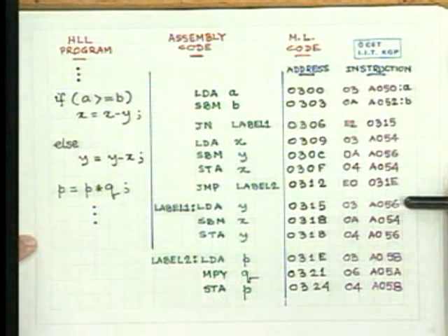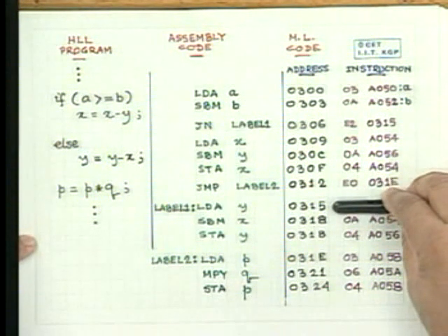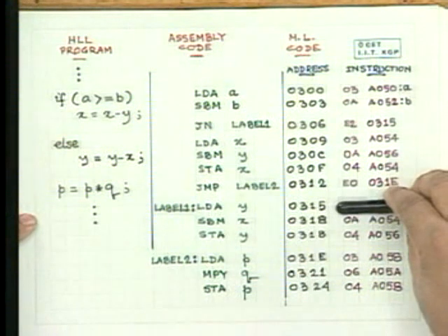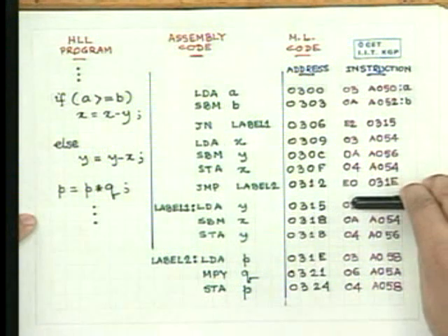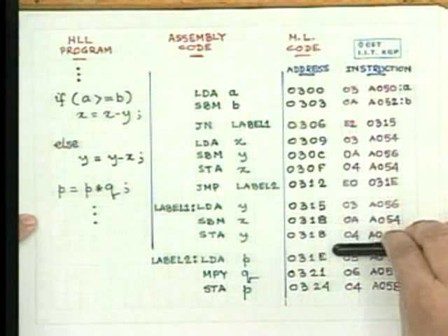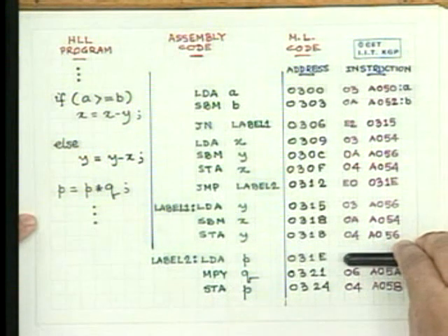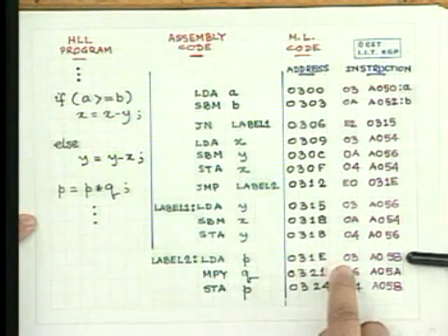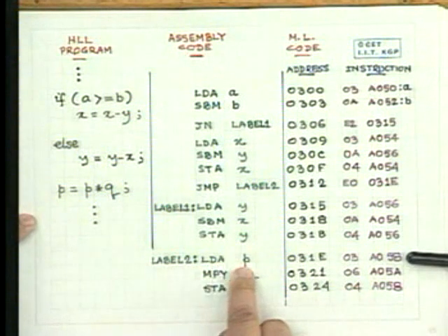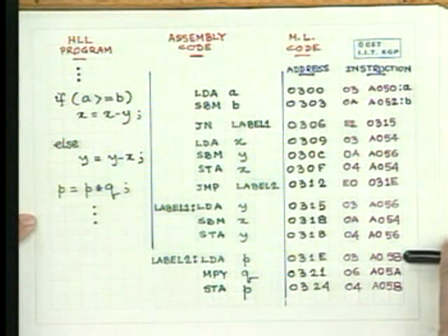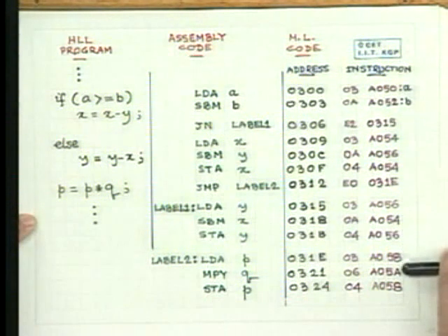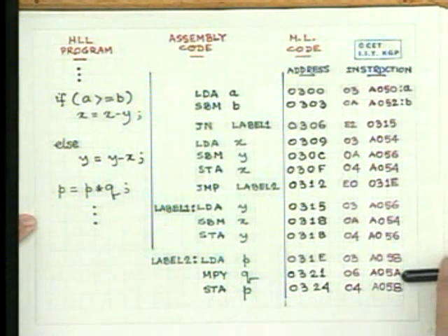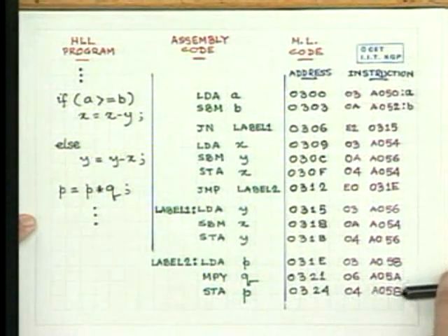As I say, at the beginning of any instruction cycle, the program counter's content gives the address of the next instruction that is executed. Since the program counter will now be pointing to 031E, the instruction execution will start from this location, that is, from the instruction load accumulator. Once it has taken a jump, the program counter will automatically get incremented as every instruction is executed, and the control flow will be sequential.